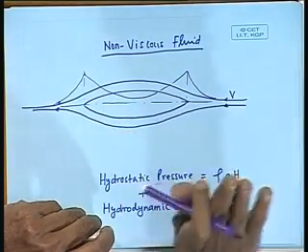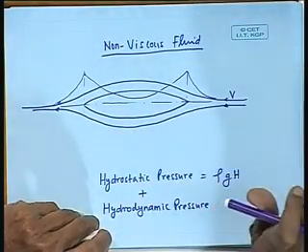We have assumed non-viscous fluid. There is no boundary layer, no friction. Non-viscous means viscosity is not there. Therefore, there is no friction between the layers of the liquid, or also on the body. We have just assumed there is no friction of any kind. It is a very hypothetical assumption, but it gives us very interesting results. That is why this assumption is made. One of the reasons we make the assumption is that when we ignore viscosity, this phenomenon is somewhat amenable to theoretical investigation. So normally we cannot visualize.